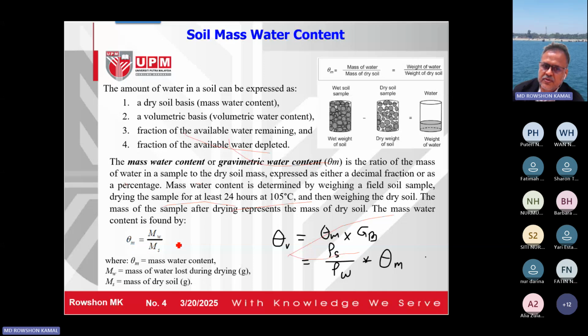And this is the theory. This one you have done, the weight basis. You take the sample, then you determine it using this formula. This is the weight of water, in grams, and the solid means the dry soil after drying. You have put your soil in the dryer oven, then the dry soil.